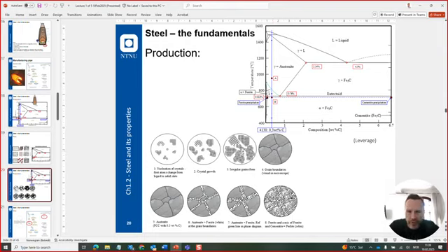When we cool down to stage 5, say, stage 6, we're starting to get ferrite. That would be around here, say around 800 degrees below the green line. And that would typically take place on the grain borders between the grains. That's when the solid state steel starts to change nature.